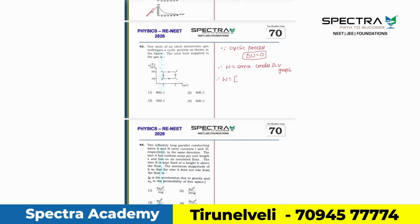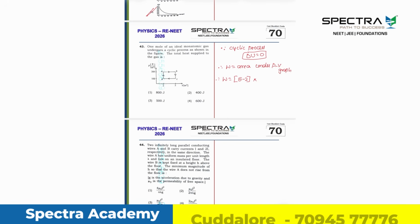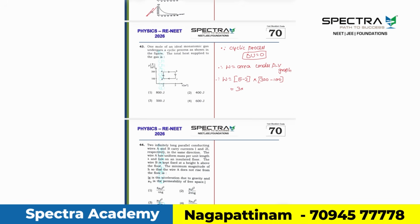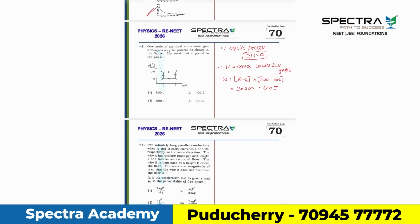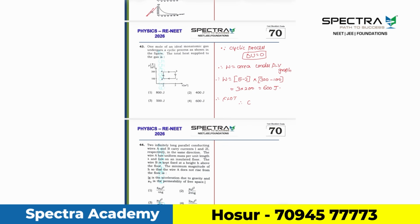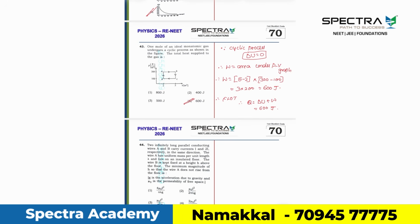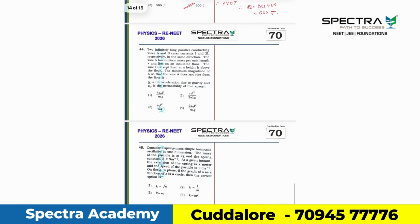Work done is equal to, it is a rectangle, right? It is a rectangle. Therefore, what is the length here? 5 minus 2 meter cube, into breadth, which is 300 minus 100. It becomes 3 into 200, nothing but 600 joules. Therefore, using the first law of thermodynamics, we can write the heat supplied is equal to delta U plus W. You will get the answer as 600 joules. Hence, we can select option 4 as the right answer. I hope it is clear to you. So move on to question number 44.